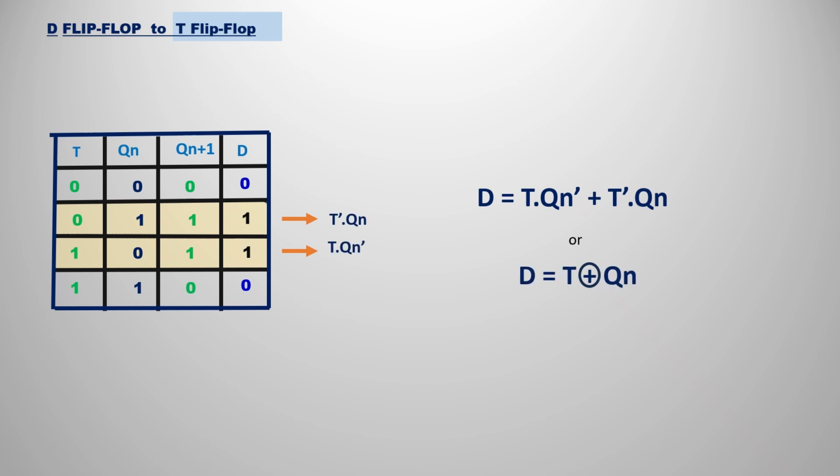Sorry guys, I forgot to mention that we have only two variables here. So we could use a two variable K map, but instead we can simply use Boolean algebra or SOP format, because there are only two variables. If you observe the output expression of D, we have only two min terms here, one in the first position and one in the second position. The first is min term m1.